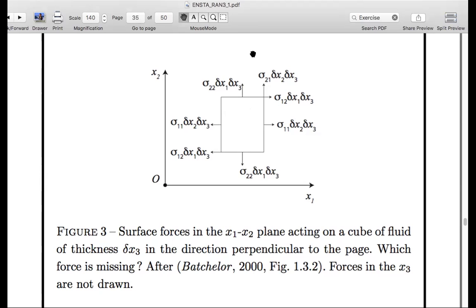So the convention was that the fluid exterior is acting on the fluid interior, and that gave this force that I've drawn here, and we expressed it with the stress tensor. So the convention implies the meaning of the stress tensor. But if that exterior fluid is causing this force on the interior fluid, then by Newton's third law, this fluid inside, below the line, is exerting a force of the same magnitude but the opposite sign on this fluid above the line here.